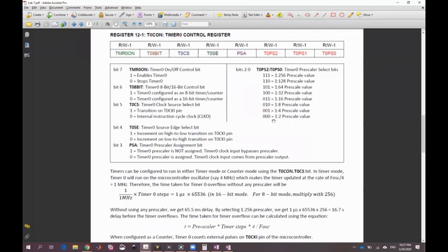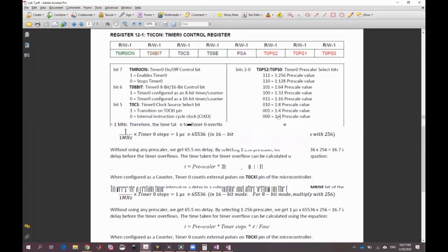So what prescaler should be chosen from here? We have these options here. If you want to assign a prescaler, then we select the prescaler bits from here, and the next bit here is the prescaler assignment bit. The prescaler assignment bit indicates whether the prescaler is assigned to the timer or not. So here we don't see an option for the timer to increment on every instruction cycle. The prescaler starts with 1:2, then you have 4, 8, 16, 32, 64, 128, and 256.